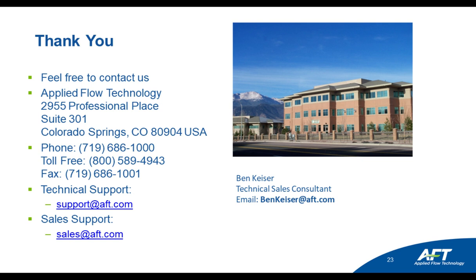Absolutely. There's a couple ways that you can accomplish that. One way is to simply change the speed directly. If you know that the pump is operating at 80% speed or 70% speed, you can model that explicitly, and the software will automatically adjust your pump curve for you via the affinity laws.